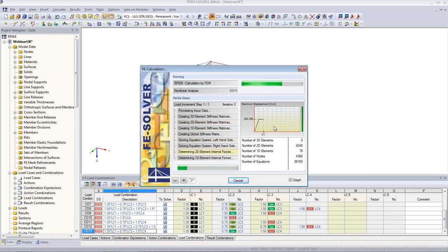These diagrams here show you the maximum displacement, and you see if everything is converging, it stays the same. If it's not converging, it may run away, and it's an indication if there's going something wrong or not. So it's an important information about the iteration process and how things are handled inside the solver.